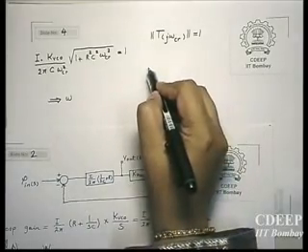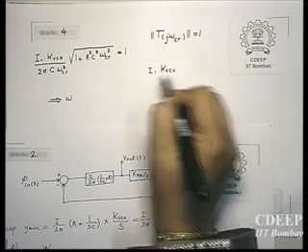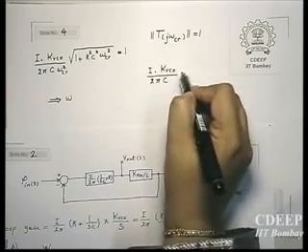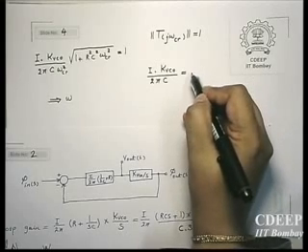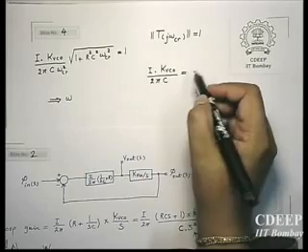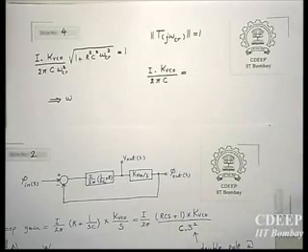So for example, I upon 2 pi C is a term that is known. I is known, K VCO is a parameter, but I tell you, K VCO is usually not a design parameter. You cannot force a VCO design with a particular K VCO.